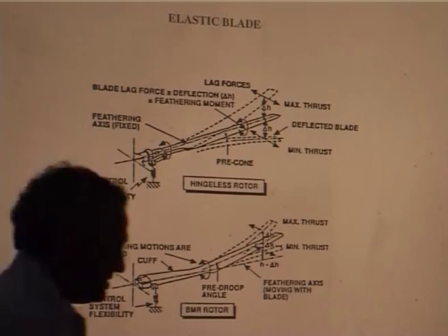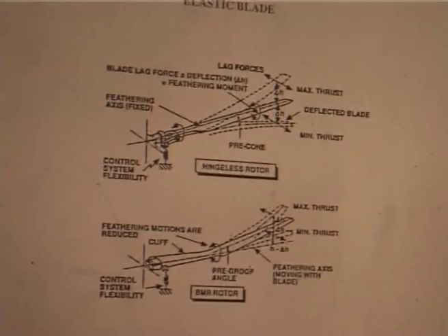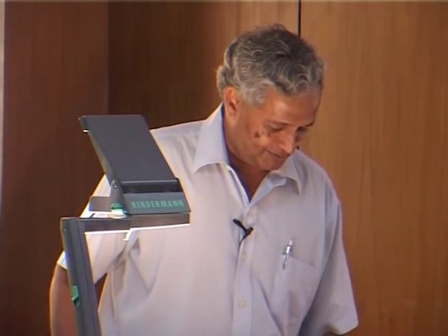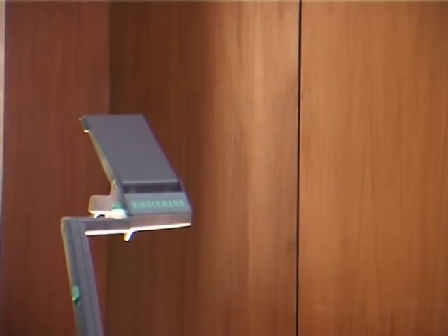introduction to you to see the complexity in the factor of safety. Factor of safety. See, sometimes I can only say what little I know, because factor of safety is always, it should have infinite life, that is the design usually. But how much load you are getting in the pitch link is very difficult to predict. Sometimes the error can be of the order of 200-300%, particularly pitch link load.